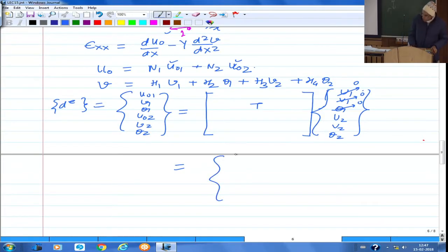So these come out as basically, for the first node, obviously they have to be 0, because if the displacements in any two orthogonal directions are 0, they would be 0 with respect to any other coordinate directions. So they would be 0 for displacements as well as rotation, but this becomes v2, this becomes minus u2, and this remains theta 2 after the transformation for the first element.